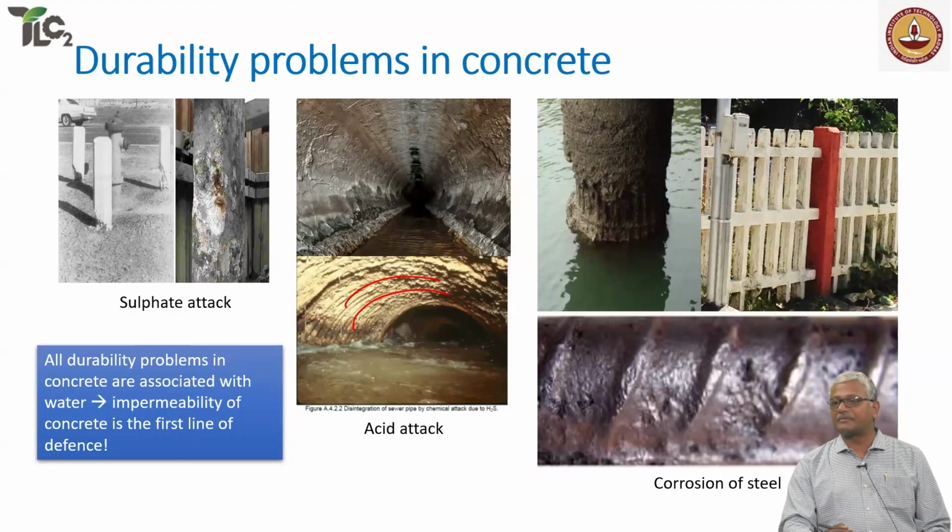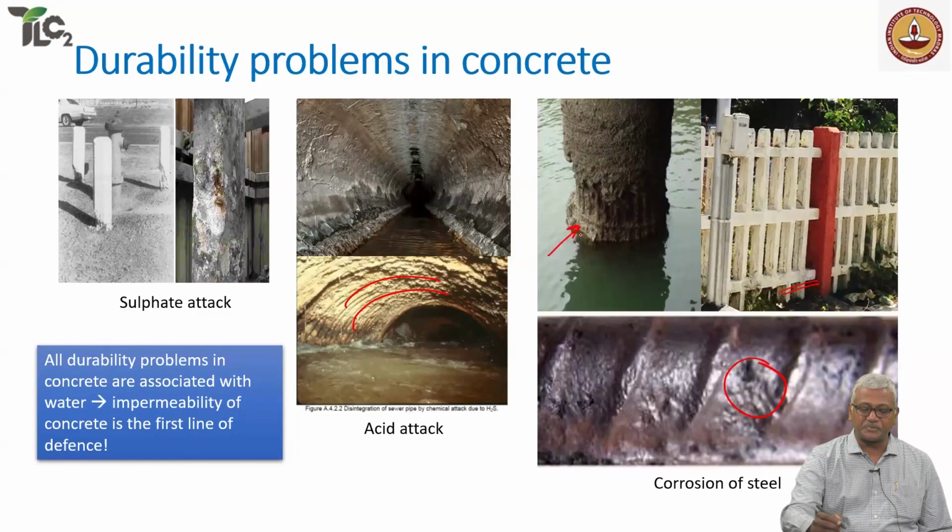Reinforcement corrosion is perhaps the biggest problem that you have in concrete in service. This is primarily caused either because of the presence of chlorides, which causes problems like pitting, or you can also have issues of carbonation, which basically happens whenever you have less cover in your concrete structures. And in marine conditions especially, you have a combination of chemical and physical attack problems that leads to a lot of damage, which is not easy to control unless you have a proper strategy for design of the concrete beforehand.